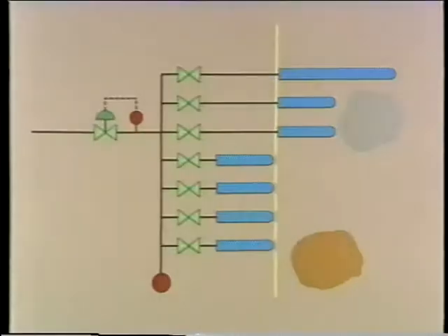The third common job we'll see done when a soot blower is in place is to check and correct for blowing pressure. A problem with blowing pressure could come from a number of places, and as we've seen, it can cause problems somewhere else too. If pressure's too high, the soot blower can be causing erosion of the tubes that it's supposed to be cleaning. If it's too low, the soot blower probably won't be doing an adequate cleaning job. And other problems, like the binding we talked about on long tube retractable blowers, might show up.